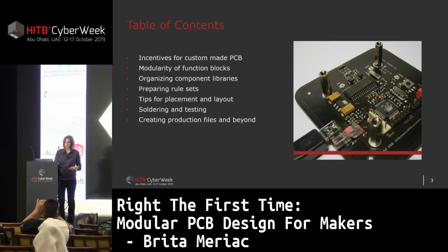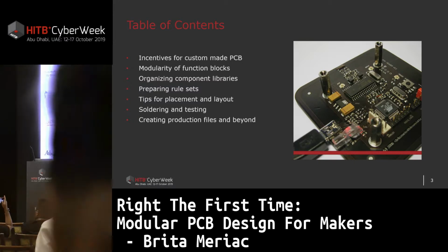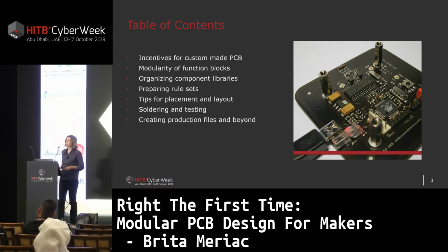And in this presentation, I will show how you can take a microcontroller project from evaluation board up to a custom-made PCB step by step. Here the component libraries and the rule set are a very important part, and I will also give tips for placement and routing, soldering, and testing, and speak a bit about optional features for a case housing.